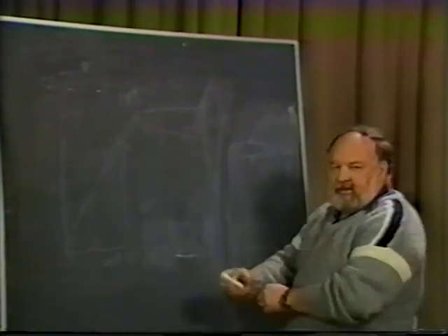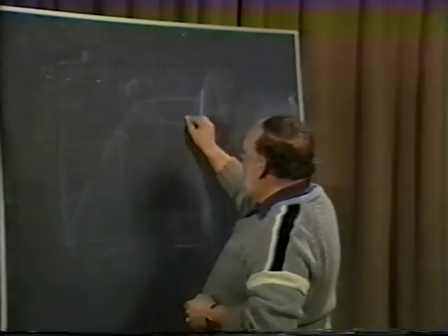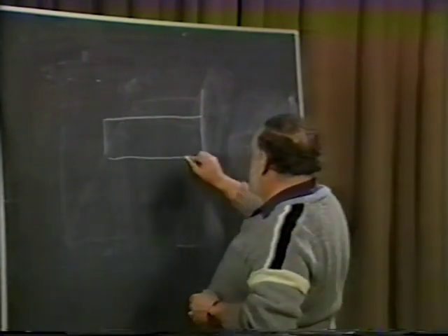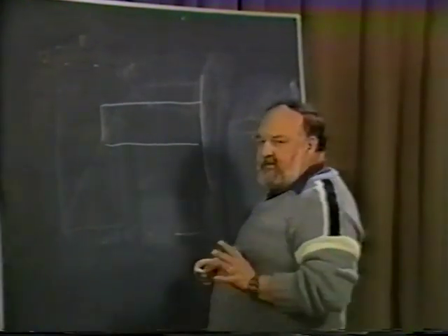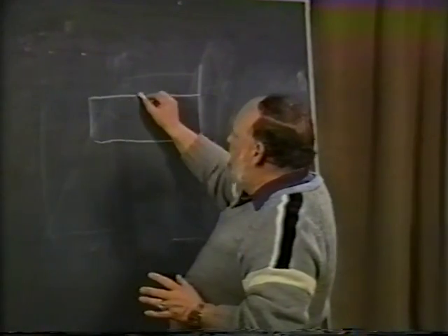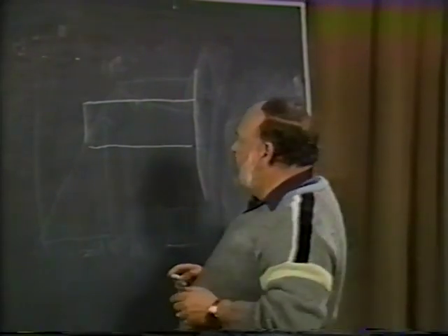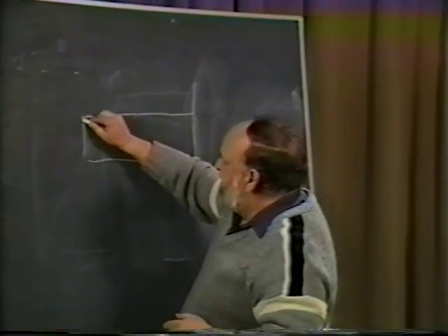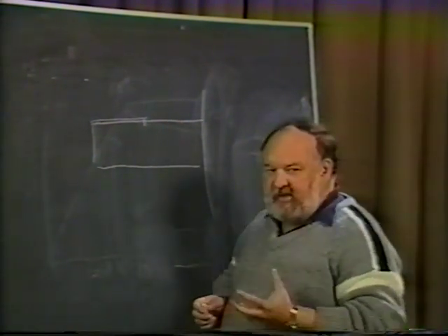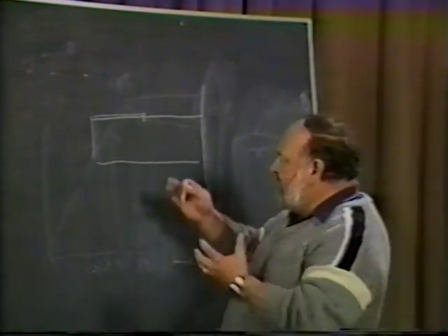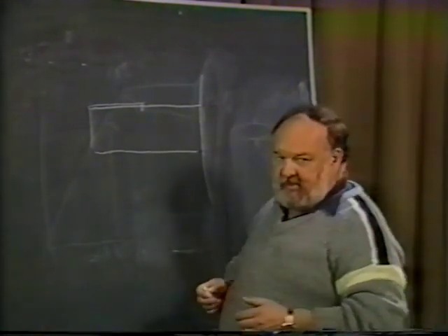NASA has been doing a fair amount of work recently in wing layouts. Let's in this case look at a more rectangular type of planform. And they have found that if this outer half, at least the outer 1/3, is handled significantly in preventing that portion from stalling, whatever the method you want to use. And one of the things they did, they put a cuff on here with a very large leading edge and actually drooped. And of course what that was doing is preventing the stall from occurring in the outboard section until quite a bit after it would in the inboard section.